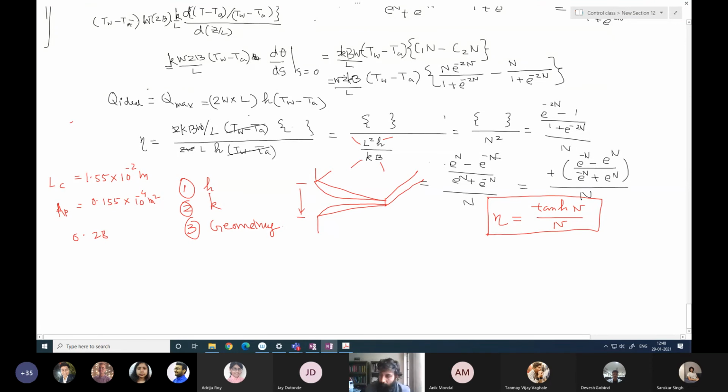And we'll consider S_E, our notation for heat generated per unit volume. Why did I change notation from Q dot to S? The reason is that we call it a source term, the heat source term. So that's the reason for this S. And this subscript E indicates the electrical source. So the electrical heat source term S_E is typically used in many heat transfer textbooks, so that's why I retained that. This is the rate, per unit time. So the rate of heat generation per unit volume is defined as S_E.